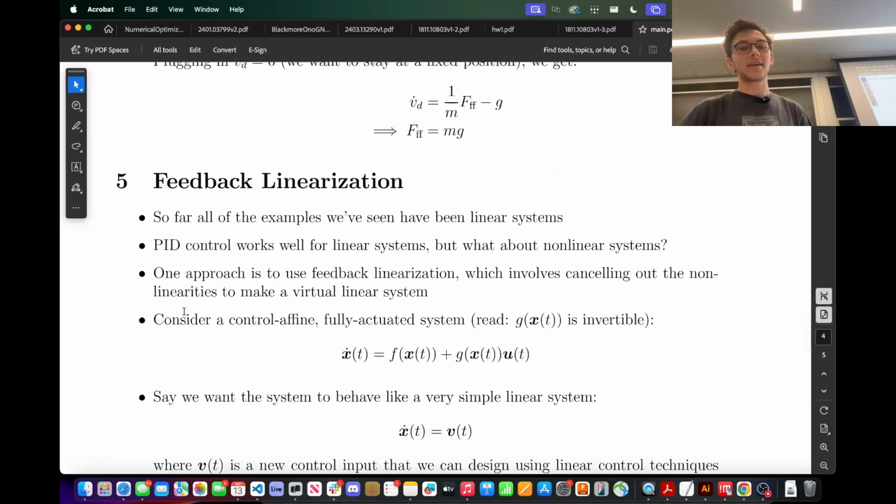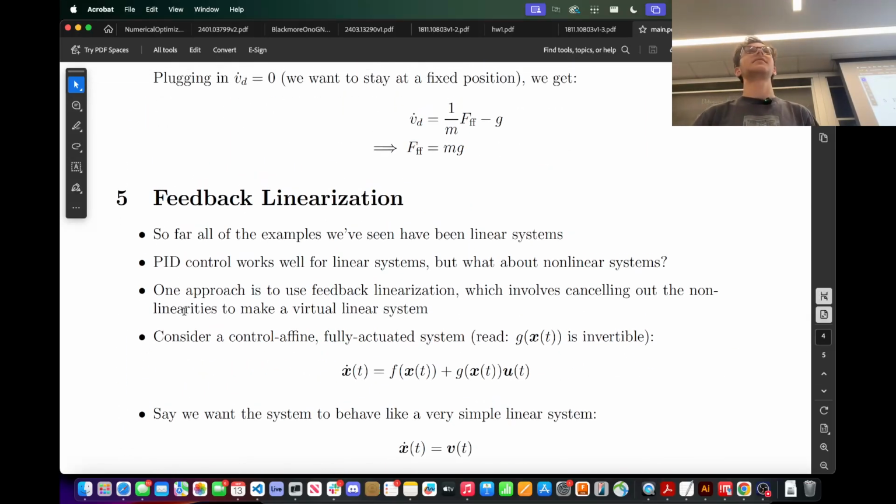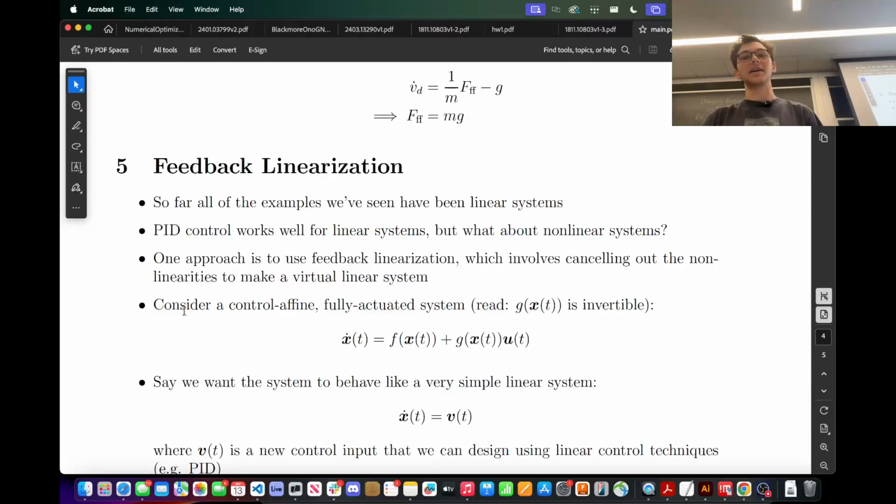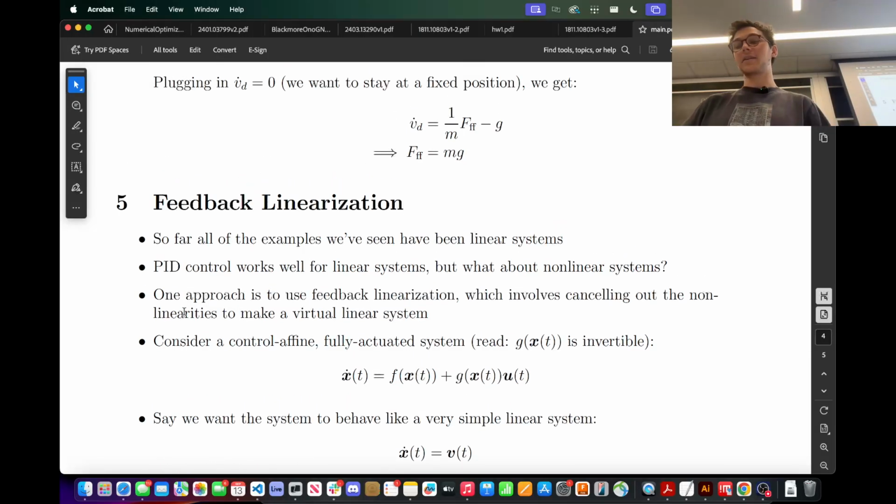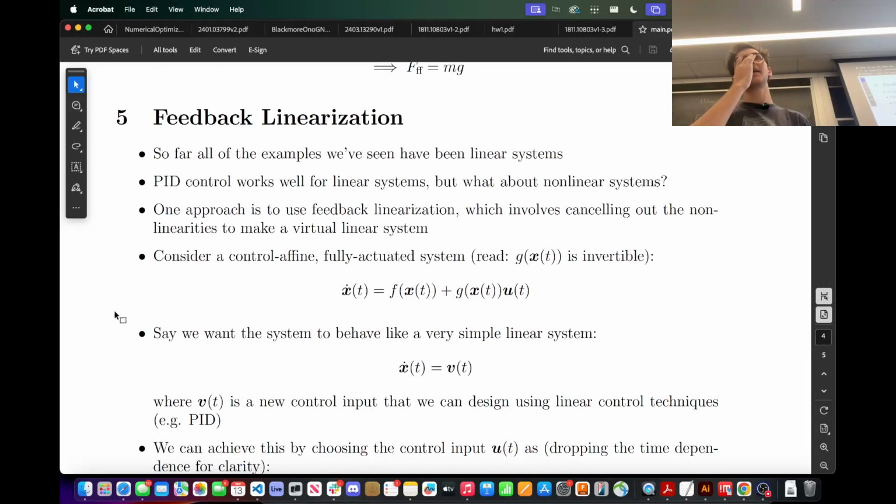The great thing about our submarine is it is fully actuated because we have thrusters. We have 8 thrusters and 6 degrees of freedom on the robot because it's in 3 dimensions. I can translate in 3 dimensions and I can rotate in 3 dimensions, so that's 6 degrees of freedom in total. And the thrusters, the things that actually control the vehicle, are set up in such a way that we can control every one of those axes completely independently from the other ones.